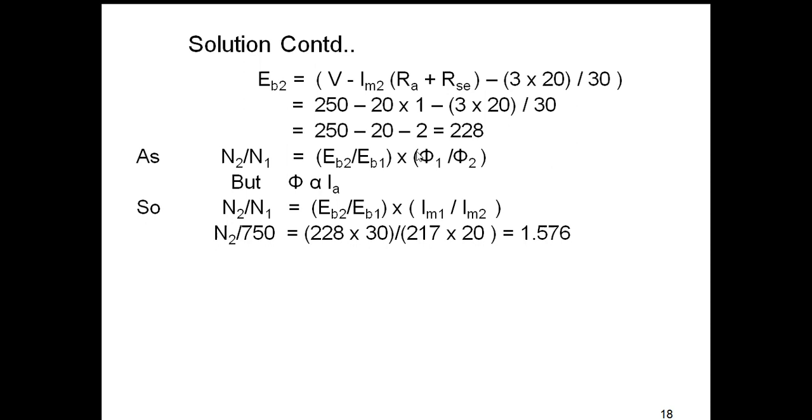We get 1.576. From that, N2 is equal to 1.576 into 750, which is equal to 1182 RPM, means rotations per minute.